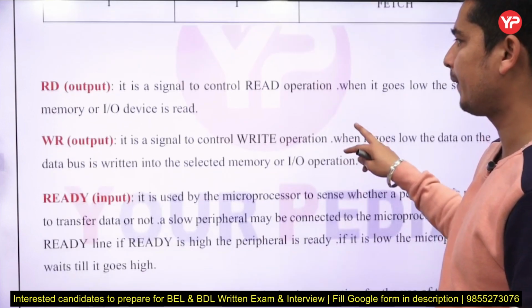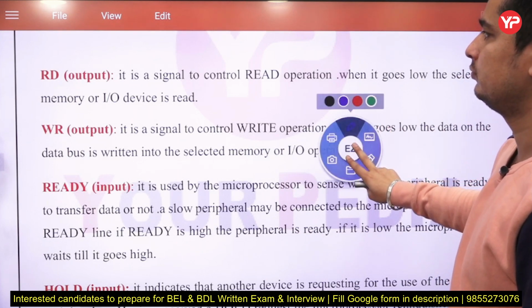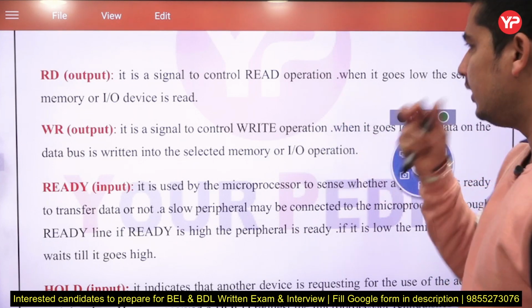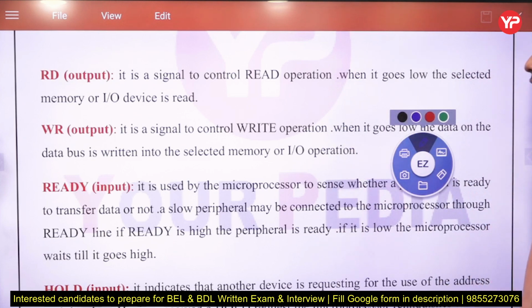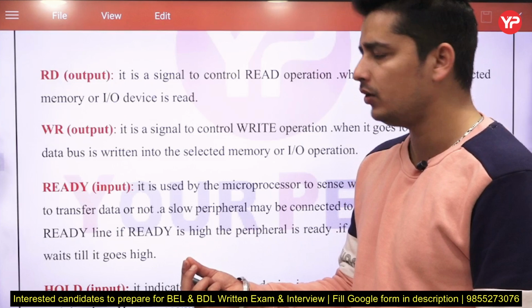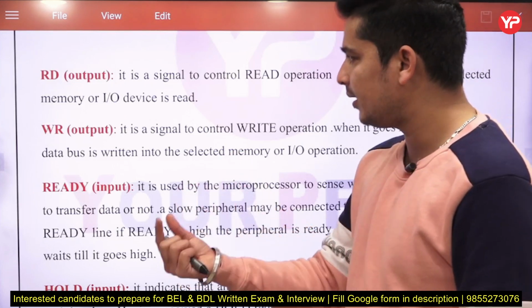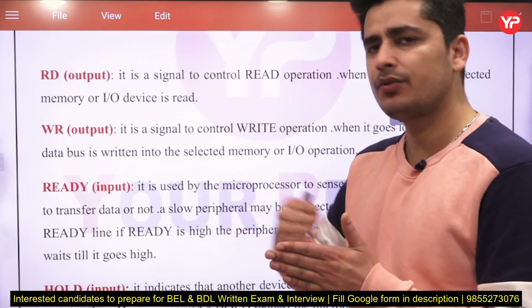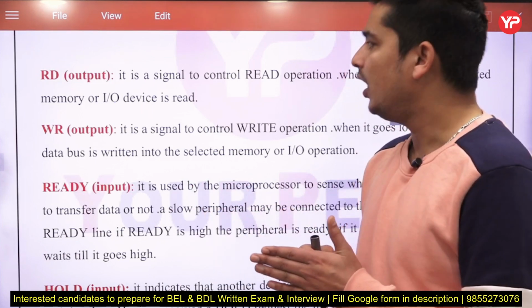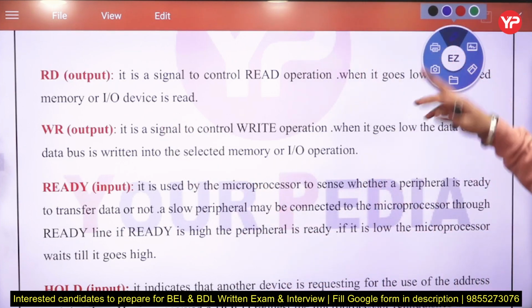RD is a signal to control the read operation. When it goes low, the selected memory or IO device is read. It is an output, and when it is 0, we are reading either from the memory or from the IO device. And WR is used to control the writing operation.